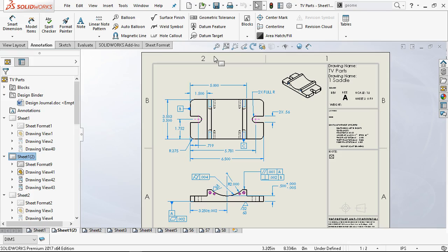So in this case, we would say that if our standard tolerances for the tool or the part are 5 thousandths, the tolerances for this fixture need to be half a thou. That's a little extreme. It's not outside of the acceptable range, but we need to make that conscious decision, not just go into it haphazardly.